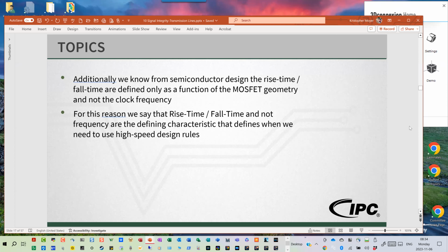So all of that frequency content, anywhere that you see a square wave, if you measure that point with a spectrum analyzer, right, you will actually see power pulses all the way into these upper frequency bands, saying, yep, you actually have pulses all the way up to these higher and higher frequency bands, not just your fundamental frequency. So yes, you are correct that all that signal gets propagated along the line. It's part of the square wave. You can't have one without the other. Does that answer your question, Vibe? Yes. Okay, excellent. Thank you.